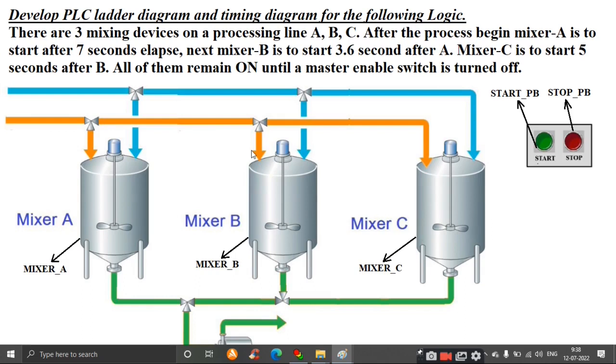So timer acts as a delay block which, when inserted in a rung, delays signals in that rung reaching the output. The time duration for which a timer has been set is termed the preset time and is set in multiples of the time base used. Some time bases are typically 10 milliseconds, 100 milliseconds, 1 second, 10 seconds and 100 seconds. Thus, a preset value of 5 with a time base of 100 milliseconds is a time of 500 milliseconds.